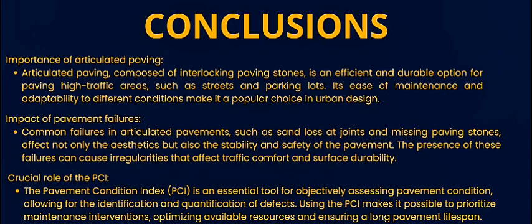Conclusion number three: the crucial role of the PCI. The Pavement Condition Index is an essential tool for objectively assessing pavement condition, allowing for the identification and quantification of defects. Using the PCI makes it possible to prioritize maintenance interventions, optimizing available resources, and ensuring a long pavement lifespan.